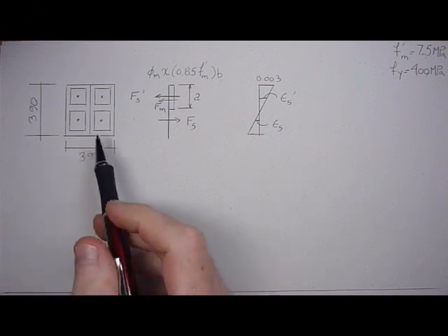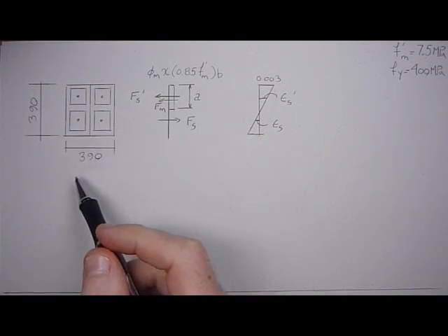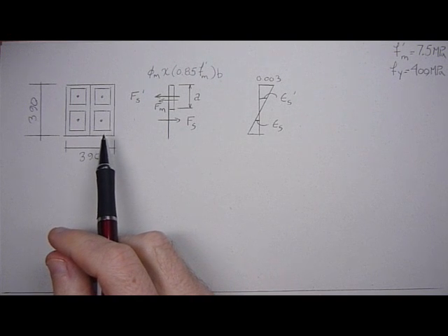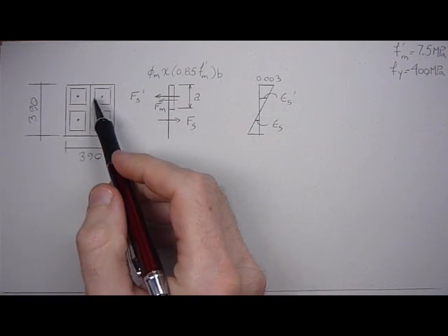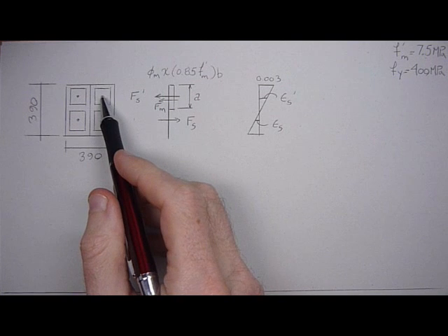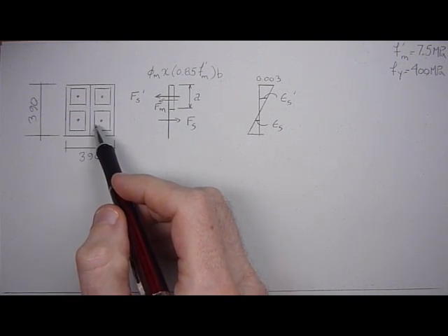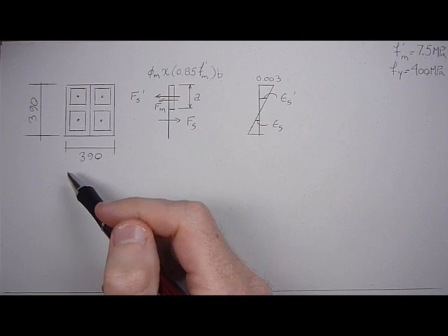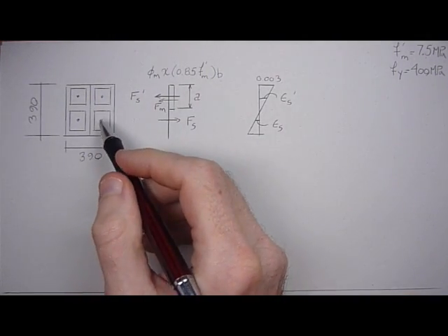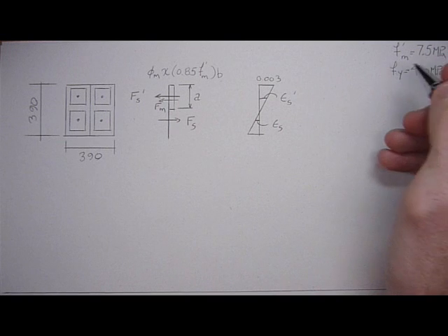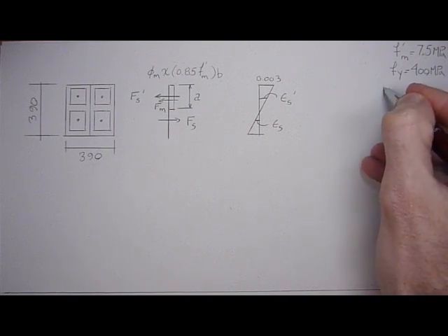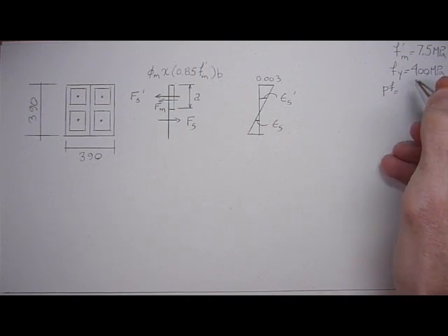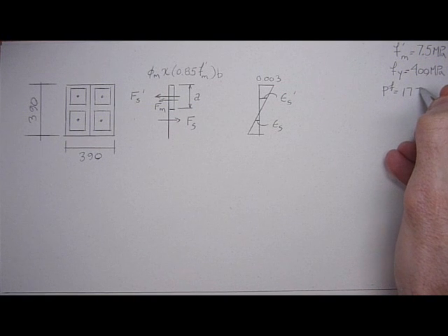Today we have a masonry pier design, and it's similar to a wall but a little bit more challenging because we don't really know if the steel has yielded, whereas in a wall the steel generally does yield. It really is dependent in this case on the axial load, and for this problem we're going to assume a P factored of 175 kilonewtons.